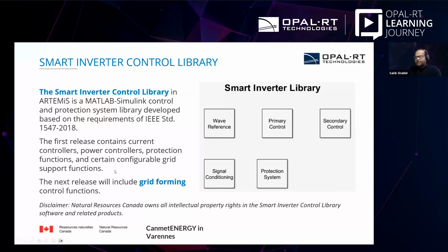It has constant active power control. It has volt-var control. It has volt-watt control. In addition, to support active power generation control, the frequency-watt control has also been integrated. In a future release, we are about to integrate the grid forming converter in the smart inverter library.